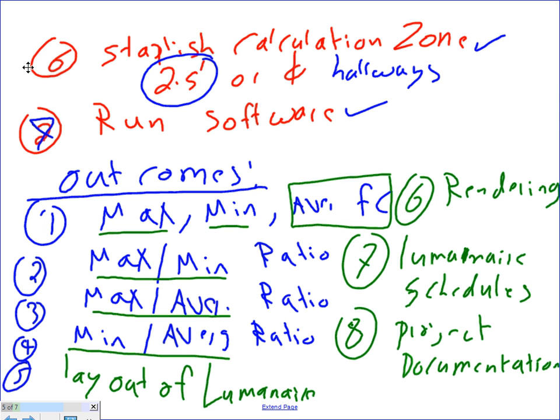Now, if my maximum to minimum is 100, this means in that little corner there, it could be 0-foot candle, and right where I'm standing, 100-foot candle. Imagine your eyes going from a 0, opening your eyes into 100, closing your eyes. Imagine the stress your eye will be under as you move and work in these environments. So that's a big deal.